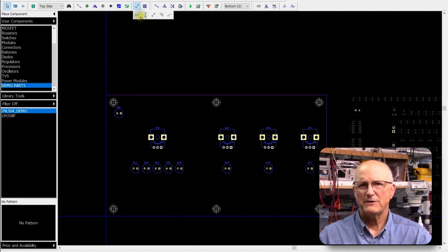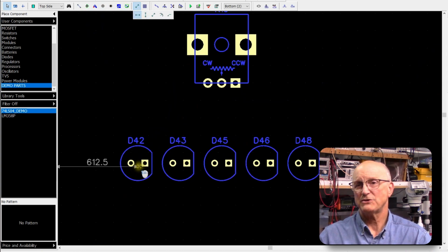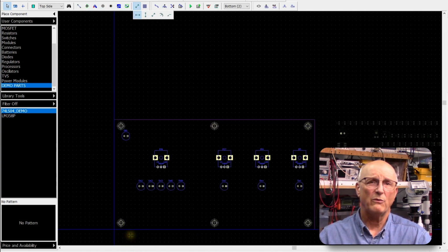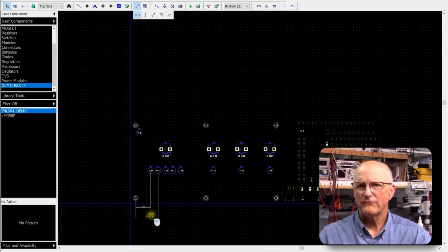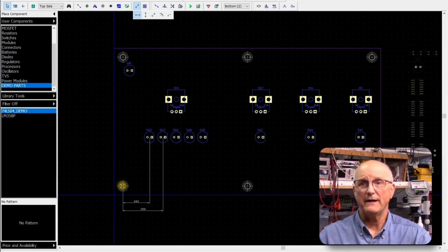Now let's place dimension lines for the folks that have to machine the enclosure. We will print these later for them. I will leave them in mils for the machining folks, but make the font larger so that they're readable.